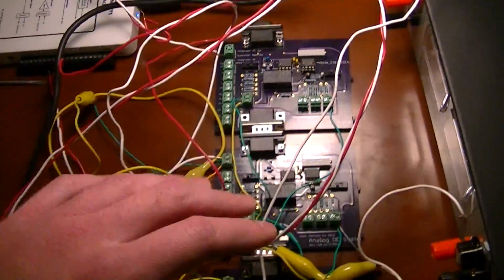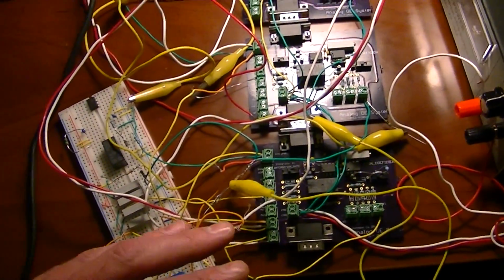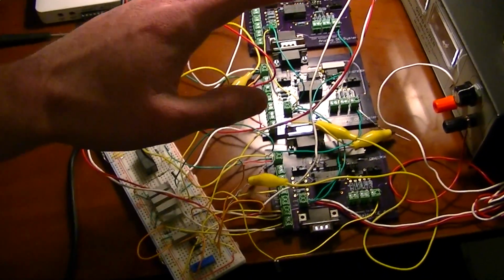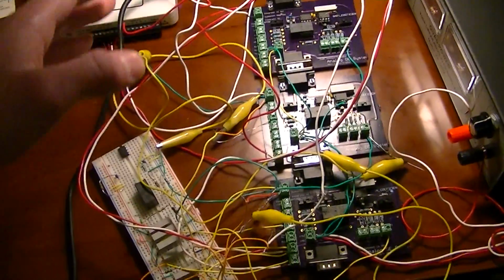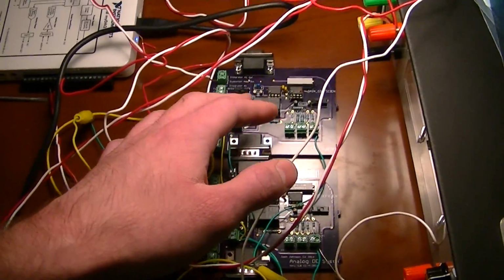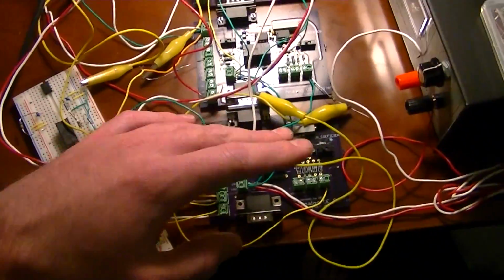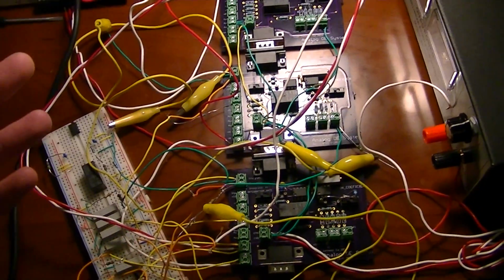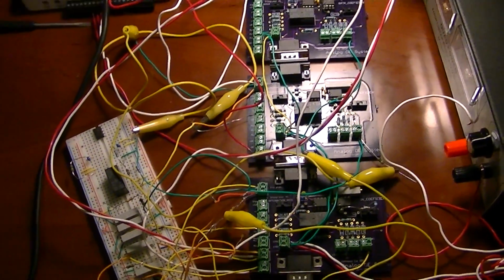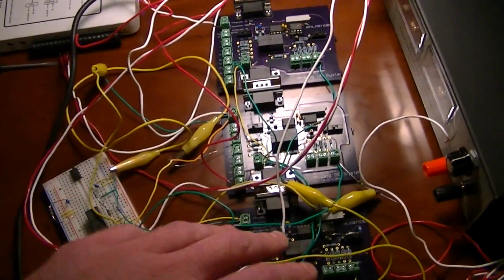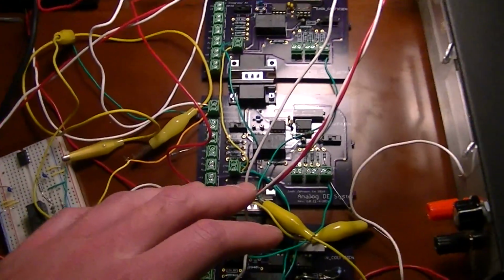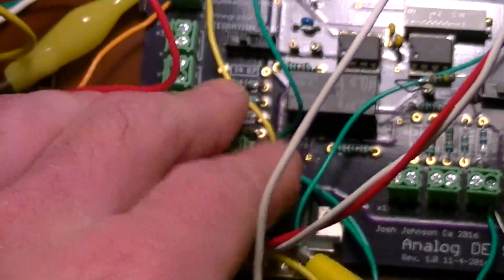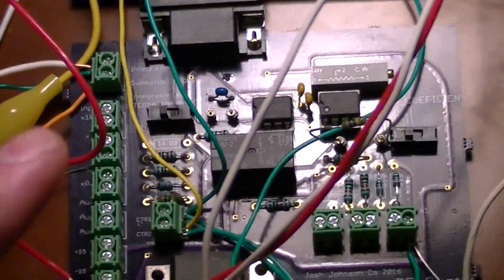And again, these 3 boards, 1, 2, and 3, were completed. And essentially, this network here is the same system as the EC1, only we're using solid-state op-amps and small modern relays. And all the components are 1%. The operational amplifiers are LF412, low noise, low offset, high bandwidth op-amps, so it's approximately the ideal op-amp, more or less. And you can see the completed board here. I'm sorry there's wires over this. If I were to disconnect it, the circuit wouldn't work.